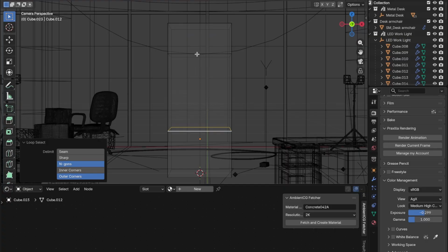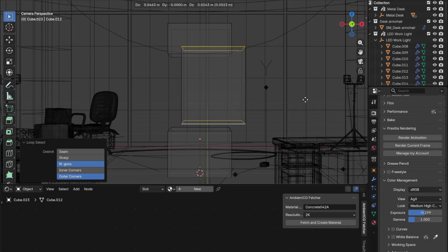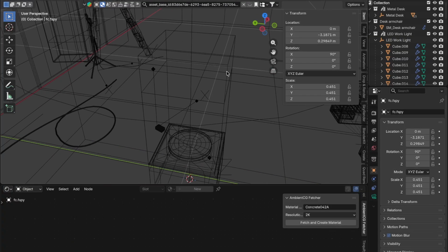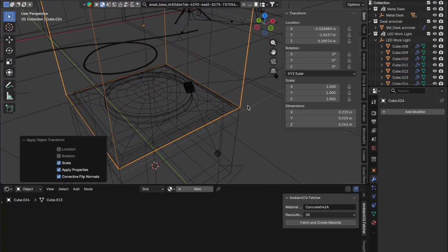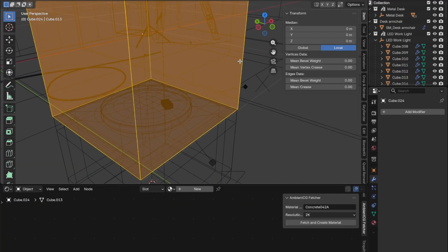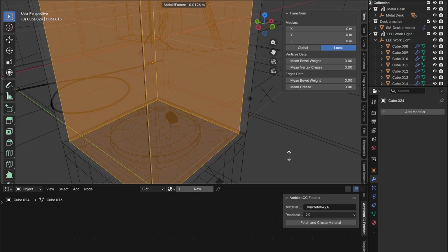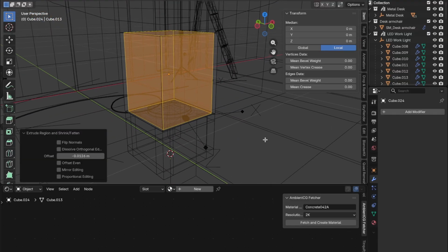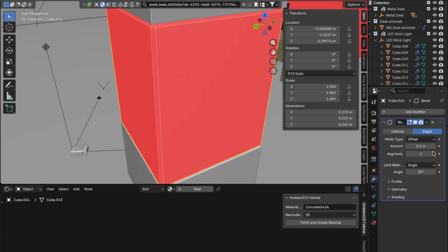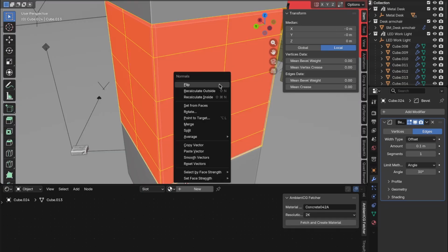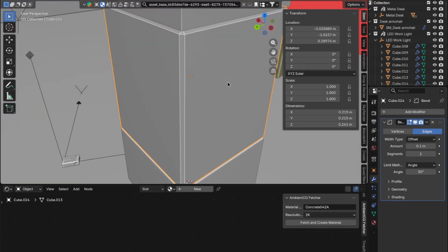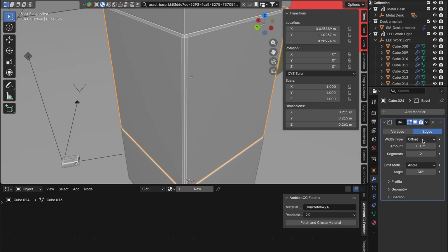Here I won't talk for long about how to create a parallelepiped, right? We will make the base, take our central part, and extrude it along the normals so the glass would have thickness. We strictly check that the face orientation is in the correct direction. Let's set the bevel on the glass. Let's set the bevel also to the thickness.